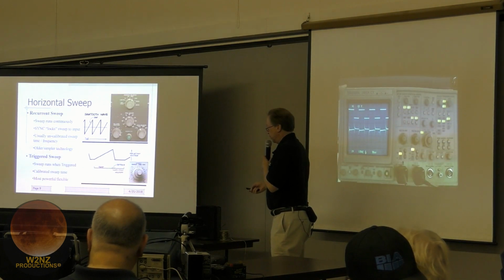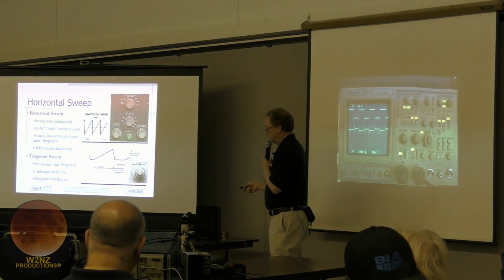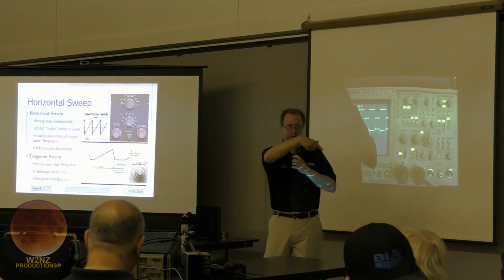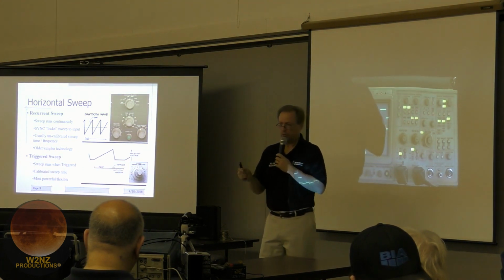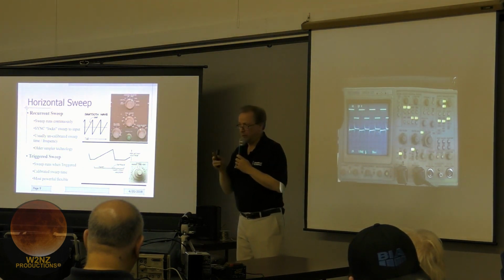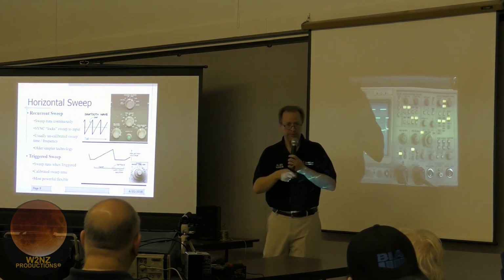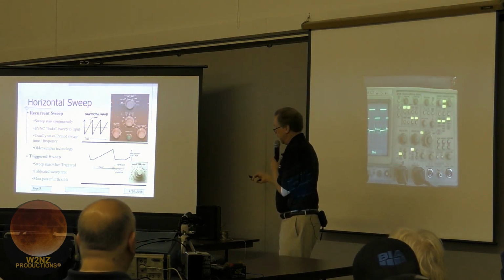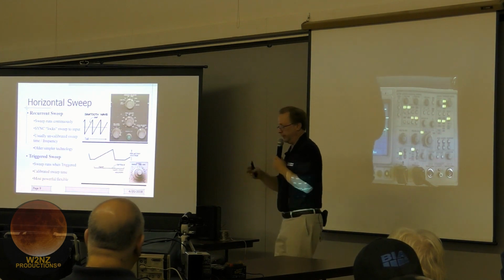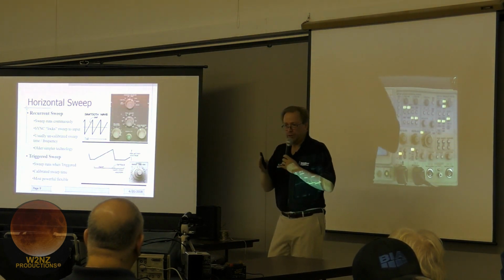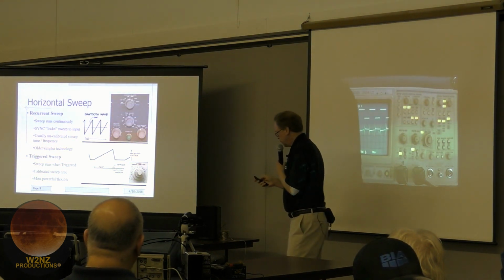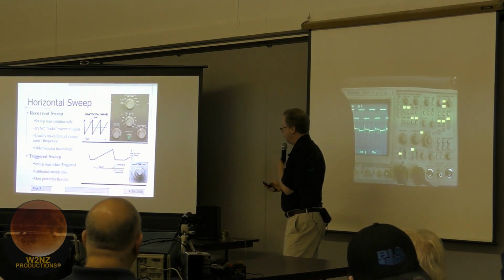So with a triggered sweep scope, the sweep will kick off and move that beam across the screen in response to some trigger. What that means is we can synchronize our waveforms to the sweep. Whereas if we just had a free-running oscillator here, the waveforms aren't going to be stable on the screen. Let's talk a little about what I mean by that.